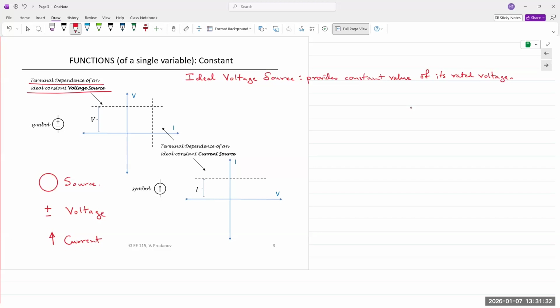So you have a power supply, and that power supply is supplying voltage and current. If you fix the value of the voltage, then it is functioning in a mode that is known as constant voltage mode. And you might see a small CV in some corner of the screen. So if it's in CV mode, we say it is a voltage source.